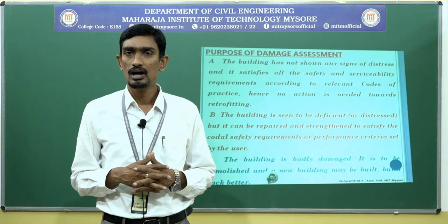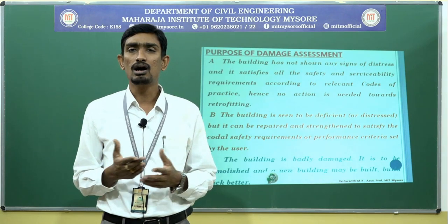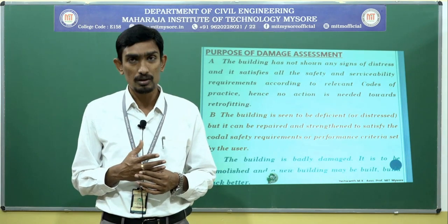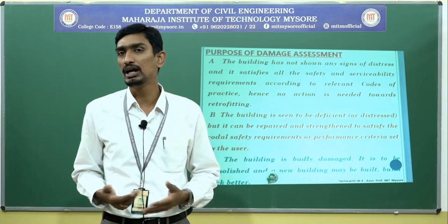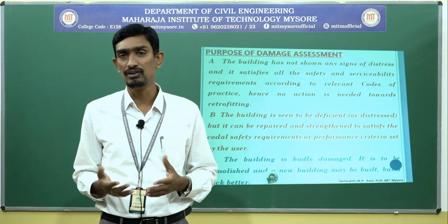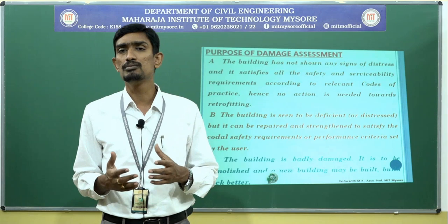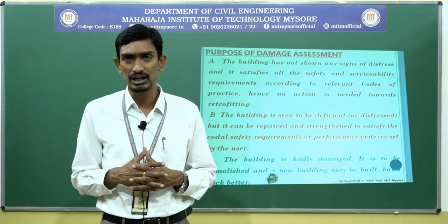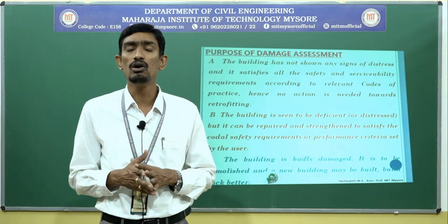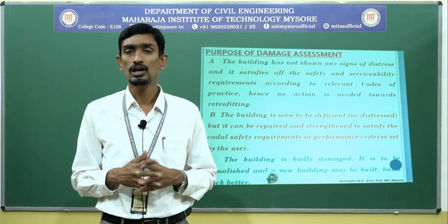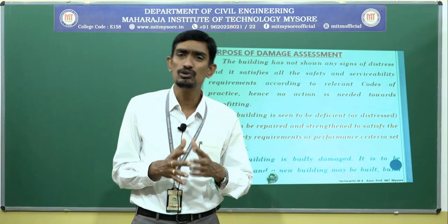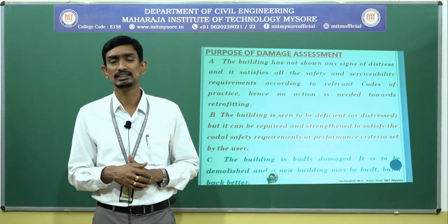Is it clear? And also you know that the column will fail under various phenomena. It will undergo buckling failure, and it will undergo crushing failure. For example, long columns usually undergo buckling failure and short columns undergo crushing failure. So these basic things you must know before going to the assessment.